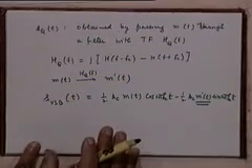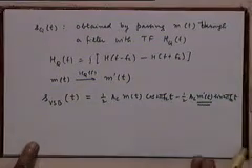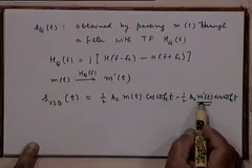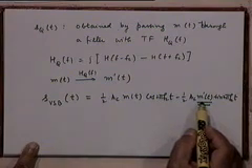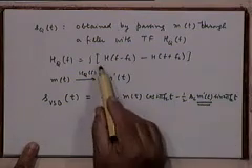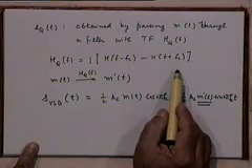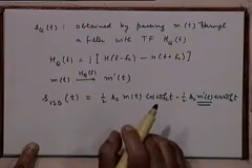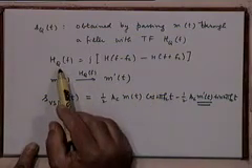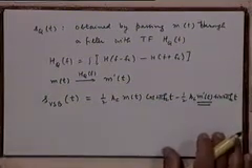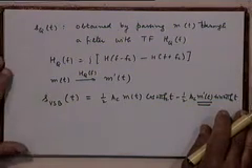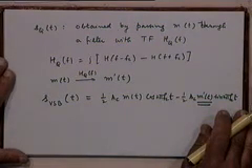So it has some similarities with what is done in the SSB case. What was in the SSB case? This was M hat T, the Hilbert transform. So we are passing MT through a special filter called the Hilbert transformer. Instead of passing it through a Hilbert transformer, we are passing it through something very similar, but not exactly a Hilbert transformer. It's something slightly different. To appreciate the difference, let's look at the transfer function HQF a little more carefully. But before I discuss that, this also gives you an alternative method for generating VSB signals.